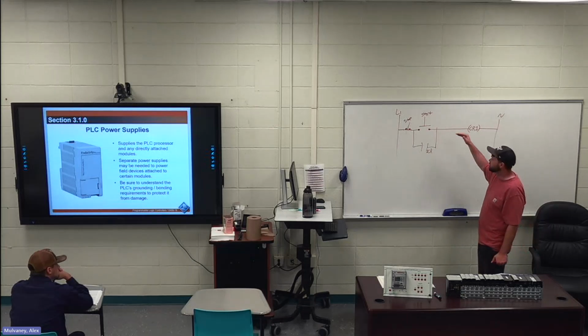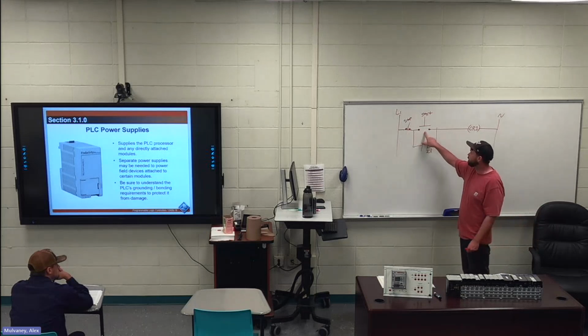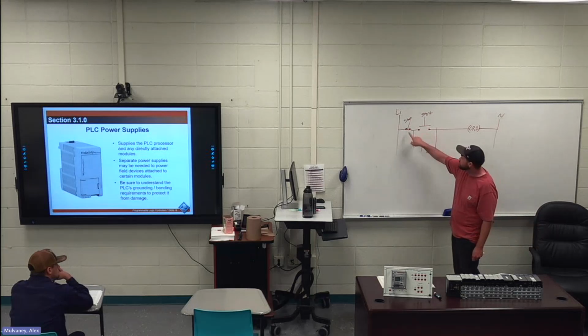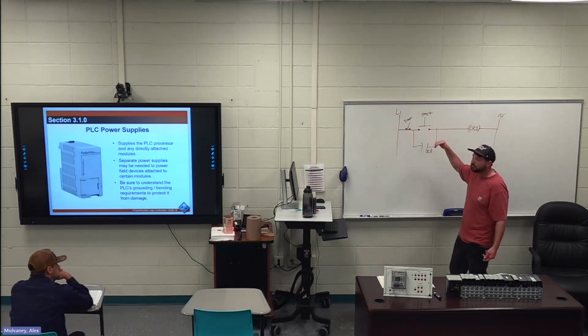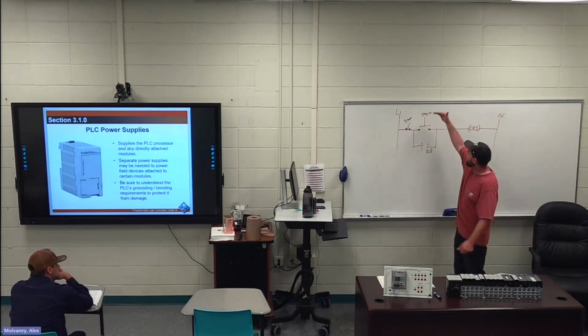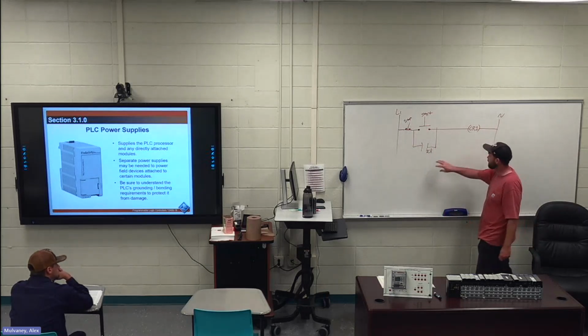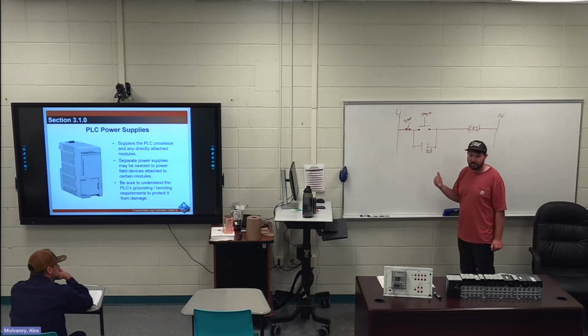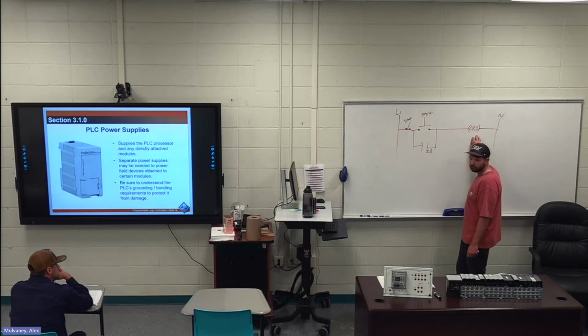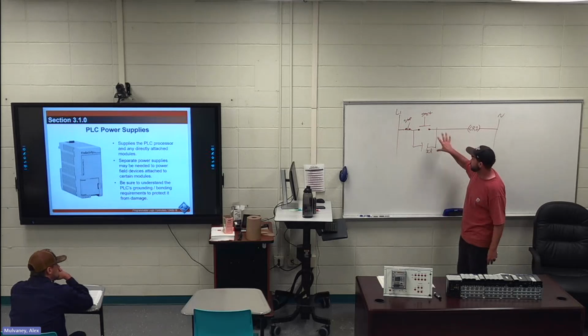Volatile memory is, say this was running. These are digital analog inputs. Digital, because a push button is either on or off. So say this system is running and I have pushed my start push button, my CR1 came on, CR1 sealed this in, power goes off. This being on is in volatile memory. It doesn't need to save that back to the processor to always remember that this was on the moment the power turned off. That data is in volatile memory, and when power comes back on, this will be like that.